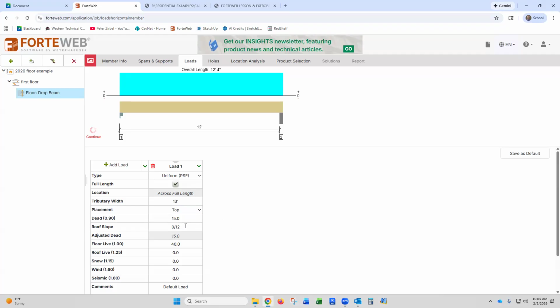Now, if this thing was a roof member, I need to know the roof slope because if I've got a really steep roof, it's got more shingles on it and more dead load than if the roof is really narrow for the same span. So I see Todd looking thoughtful here. I'll try to do a drawing to explain it.